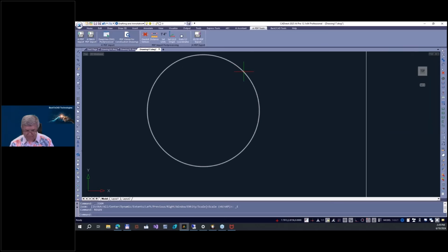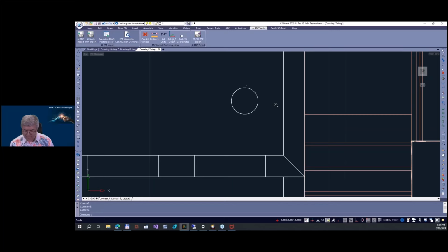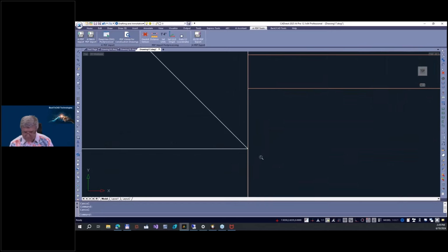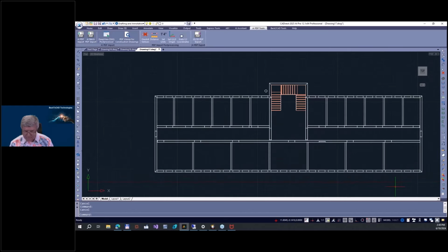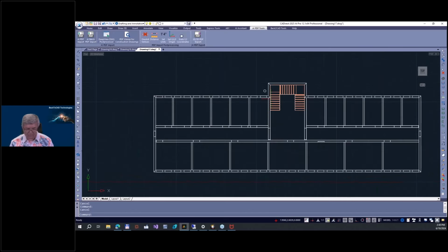The circle is a perfect circle, okay. We have here, look at the walls, perfect quality. So this is a perfect drawing you can really use. Of course, you never know what the coordinates are because they're PDF coordinates, but it's very easy. Scale the drawing. I don't know what the distance is. Maybe it's 100. You have to tell it, scale the drawing so that this distance will be maybe 100.